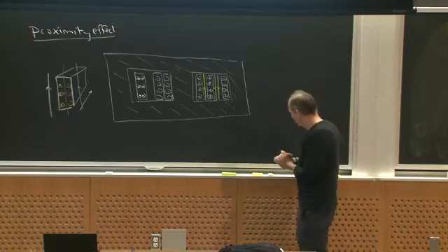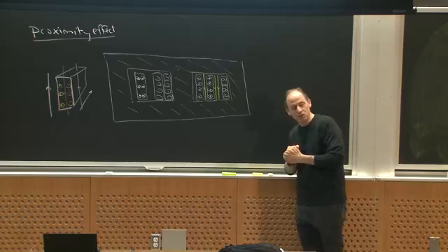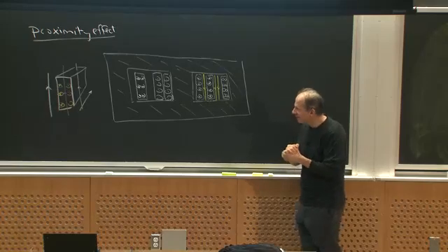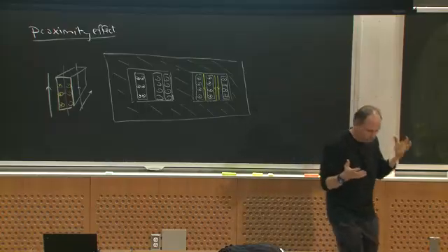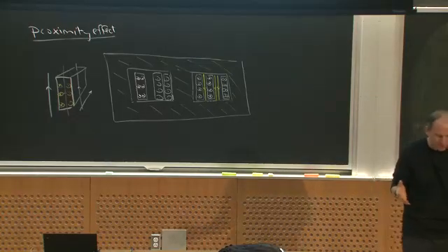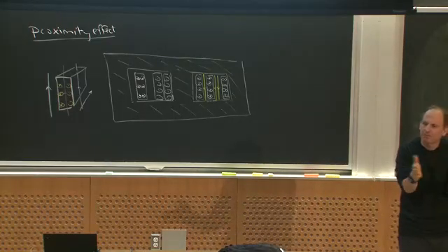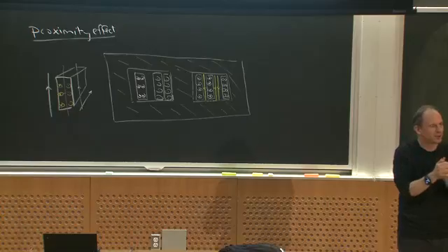And in fact, what does that say you should do? Typically, because of skin effect, I wanted my wire to be on the order of a skin depth or thicker, or at least my strand diameter for my litz wire.